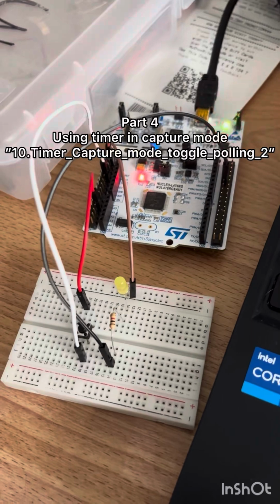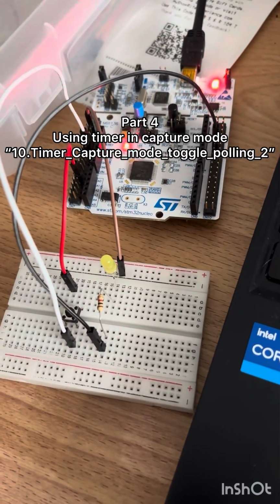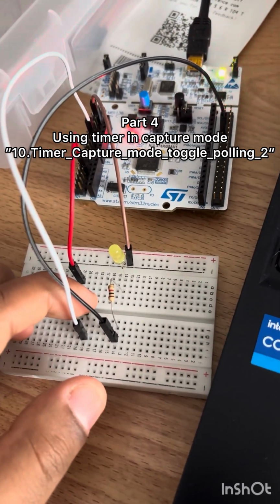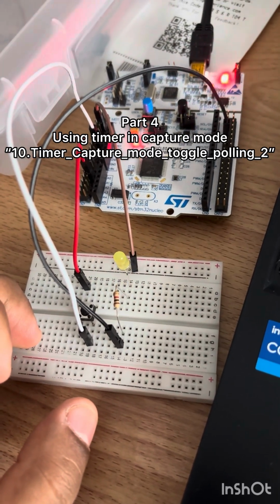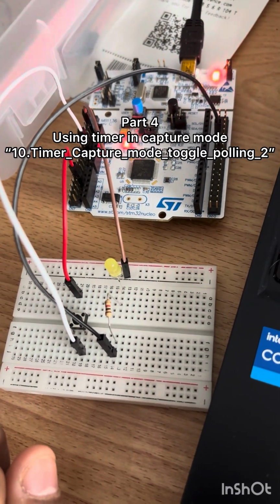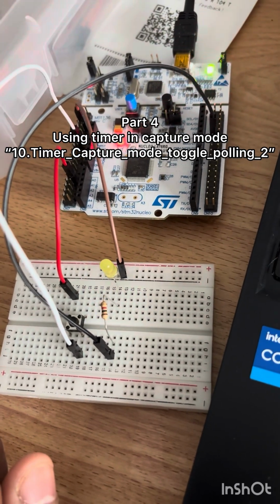Right now, since the ARR value is set at maximum, the delay time is also set at maximum. But when we press the button, as we can see, the delay time has changed to the amount of time we have held the button.